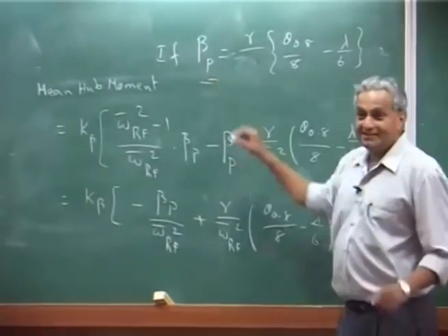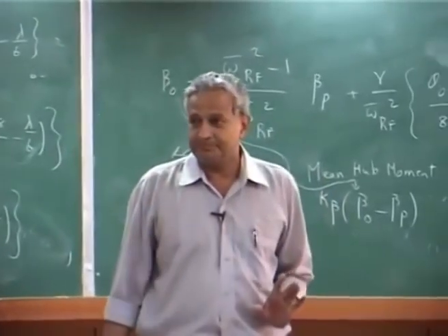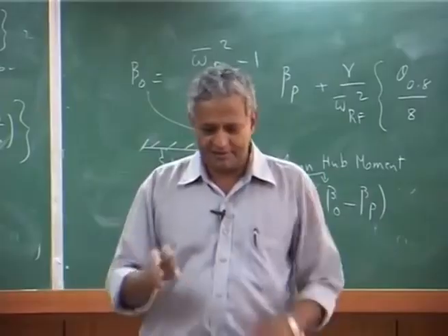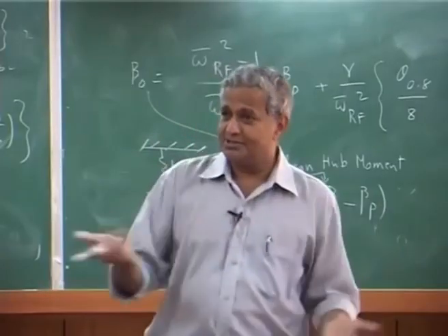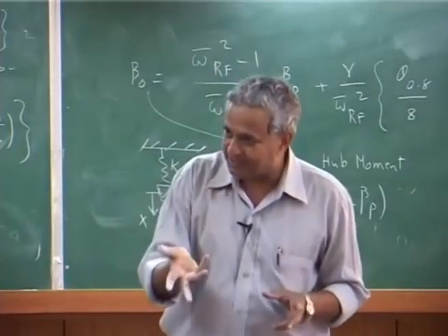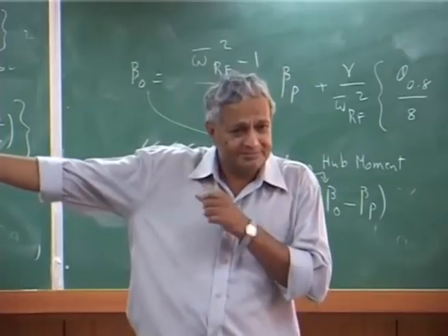Now, you know why rotor blades are given slight precone. If it is a pin, that moment is 0. Centrally hinged, no problem, but the moment you put a spring, it is like a cantilever first mode.